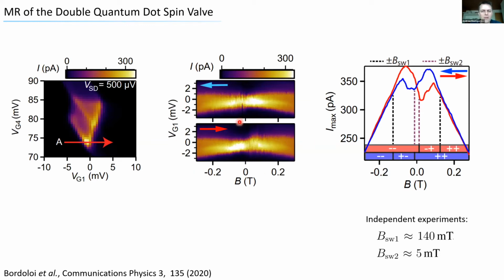And you already see by eye, here we have large conductance, here a smaller one, and here it's inverted. If we extract the current amplitude in the upsweep, this curvature here is the magnetoresistance of the bare wire. But then when the first ferromagnet switches, we get a strong change, and when both switch in parallel again, we go back to the original curve shifted in some other direction.